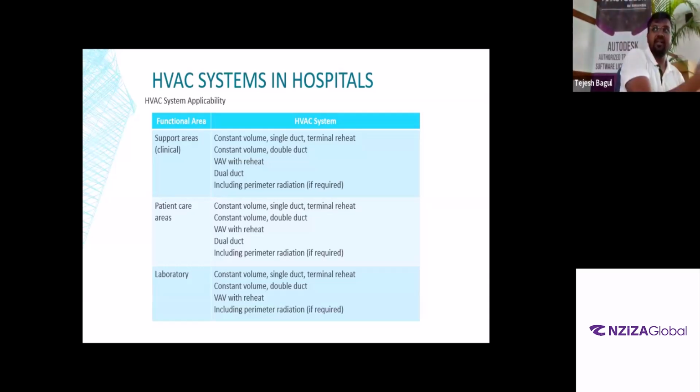The reason I'm talking about the VAV ducts over here is because we have done a very extensive exercise of calculating what the heat load is. Yesterday, I gave you an indication of how big a trip 1 kg of refrigerant would equate to if it leaks. So when you have the VAV box, which is modulating your airflow, that is basically tracking your heat loads in the building. Your fan coil unit is sized for 2 kW, 1.94, and we have upsized it to 2 kW. Not necessarily, in the morning, that room might not need the entire 2 kW of cooling. It might only need 0.5 kW of cooling. At that time, you can use the VAV box to reduce the airflow. Is that making sense?